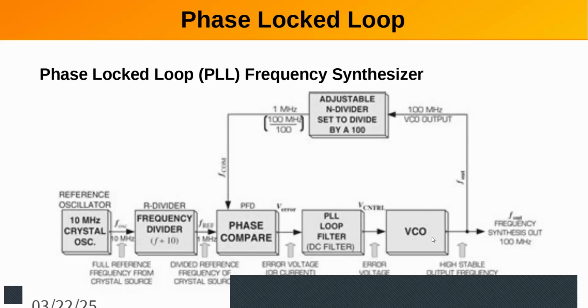So at the point where the VCO matches this frequency determined by the ratio of these two things, it's essentially going to be locked in phase at that frequency. If the frequency's off, you're going to get an error signal, which is going to drive it back whichever way in order to get it back to that point where the phases compare.